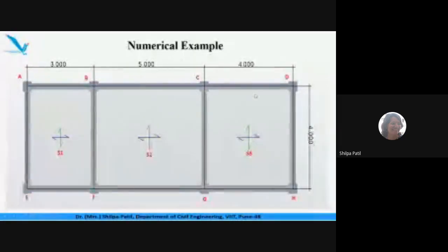Now here we want to design the side beam, which is ABCD, a continuous beam on the top. Now we are observing the plan, that's why I'm using the words top and bottom. On the top of ABCD, this line, there is nothing, and at the bottom side there are the slabs. In other words, ABCD is a continuous beam with nothing on its left-hand side and slabs on the right-hand side. So beam ABCD is like an L beam. It is a side beam, so it will behave like an L beam and not like a T beam.